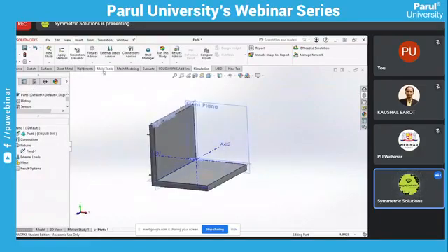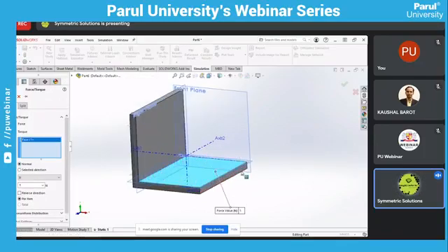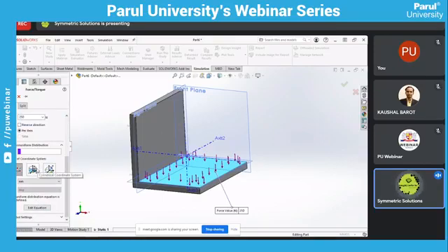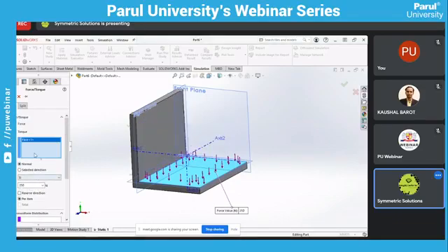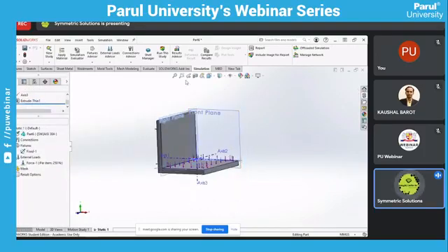Okay, now if you want to apply some external loads as boundary conditions, then force, torque, pressures, gravitational force, centrifugal force, bearing load, we can apply anything. Like I applied some force on this face. How much force? Something like 250 Newton. Fine. This is a static force, right? If you want to apply some non-uniform distribution, we can also apply non-uniformly. Okay, this is uniformly applied.